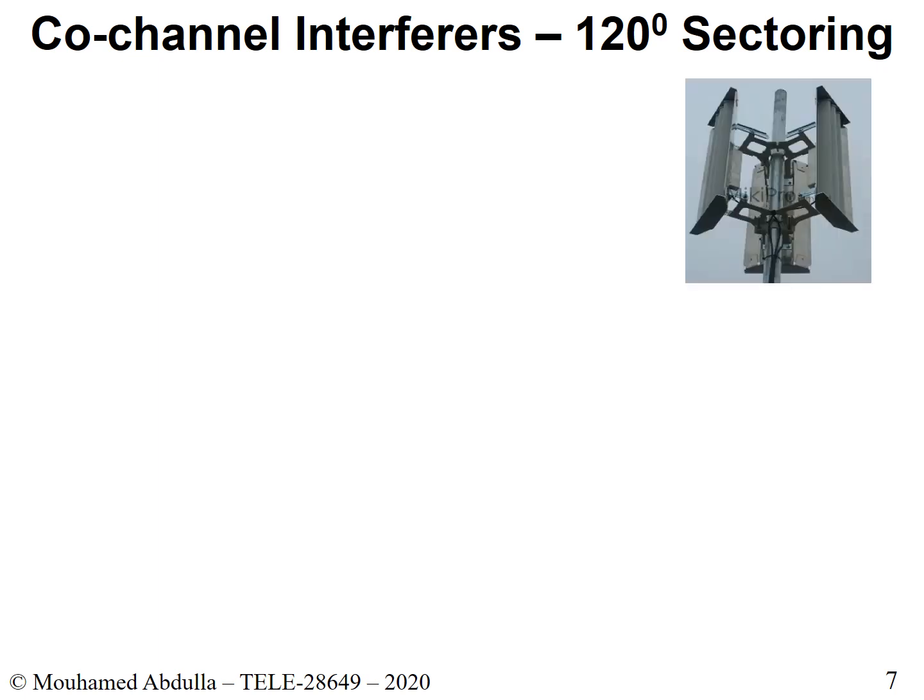This is a picture of a base station, of an E node B, where the antennas that you have are sectored. So as you can see, you have 3 different antennas. They are totally independent, and they have a certain coverage region. So this covers a 120-degree region of where the antenna is propagating. It doesn't propagate in all directions. And this as well, the same thing, propagates within a region of 120 degrees. And then the same thing with the other one. If you add 120 times 3, that creates your 360.